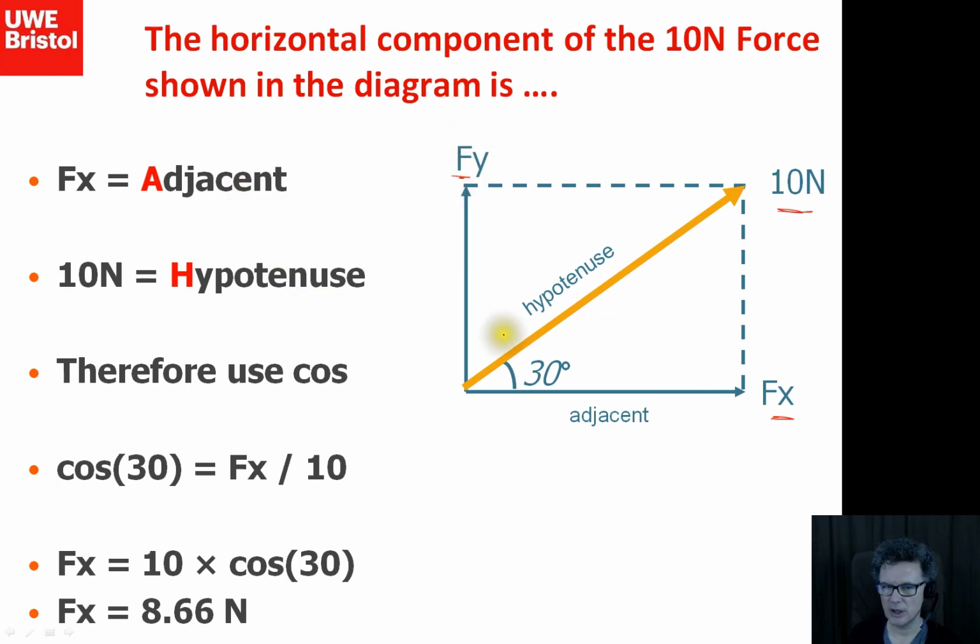So we have to remind ourselves of the basic trig. If we were looking for the force in the x direction, we'd think, okay, well, that's the adjacent. If we've got this angle here, 30 degrees, and the nice long line that's always at a diagonal, well, not always, but it's the long one, that's forming part of this right angle triangle, that's going to be the hypotenuse.